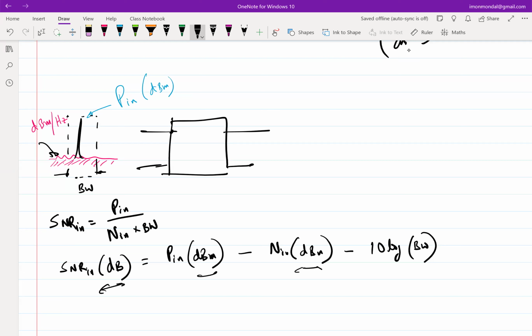Okay. Fine. So now I pass it through the two port. Let's say the two port has a nominal gain of G. Right. So this is another thing about RF. G is typically referred to as the power gain, and sometimes obviously it is also a conductance. Right. So be careful of which G we are referring to each time. So G in this case means power gain.